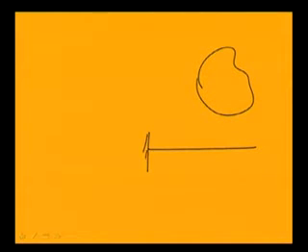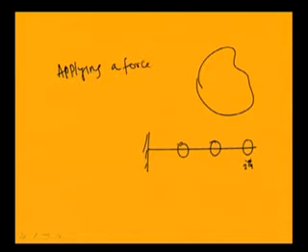Let this be the system that you have just now derived. Let us take this system and apply a force at the ith station. Let this be the ith point, applying a force Fi at i. The work done will be equal to half force into displacement.